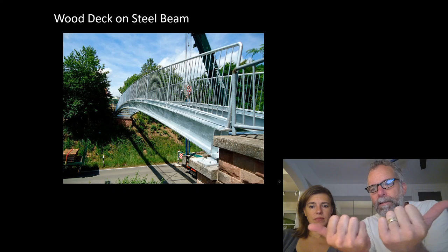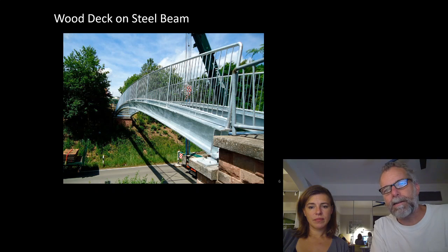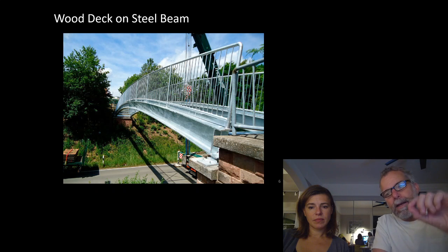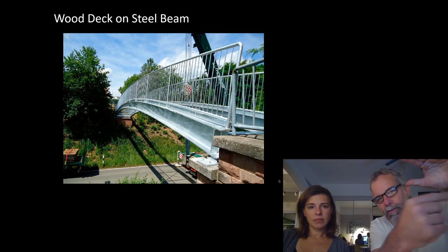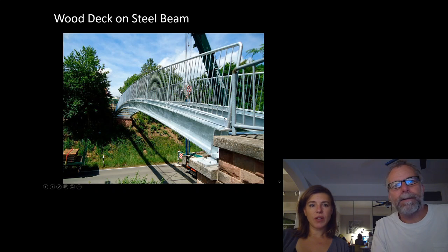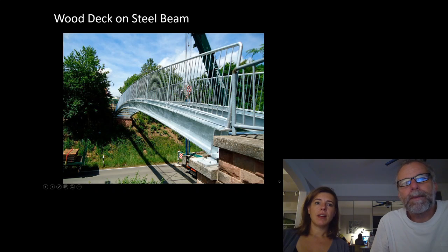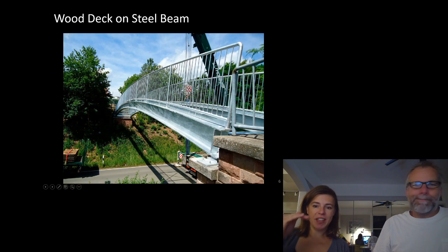The outward thrust at each end would be gigantic and unmanageable, so it would be designed like a beam. The curvature is about getting enough height over the thing that you're trying to traverse, so that you don't have to have massive upstands here as well. It also means that when deflection happens, it's not as visible to the eye, so there are some built-in bonuses there.